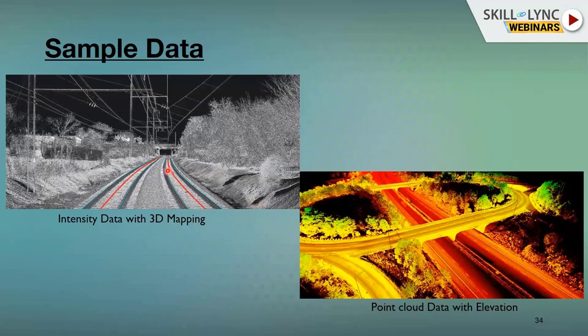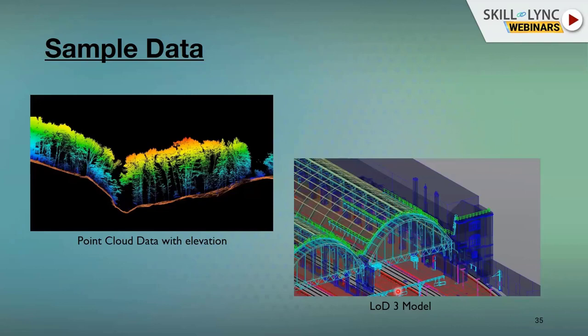All right. So while seeing this data, you can imagine or say to yourself, okay, this data might have been captured from mobile LiDAR. Yes, of course, this data can have been captured using mobile LiDAR instruments. So you can see the elevations, and the data looks like this, and this is the intensity. Intensity has only two values, black and white, 0 or 1. So this data has been captured from terrestrial LiDAR scanners.